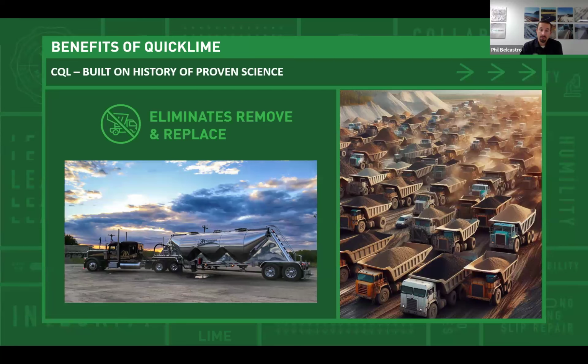But when I go to the sites, I'm one of the few people that are smiling because I know that clay soil is primed for lime. We can modify it. We can get some true stabilization on it. We can use what Mother Nature has put in that soil, the natural pozzolans, silicas, and aluminas, to generate those bonds that we're going to use to generate these needle-like cementitious and pozzolanic reactions for us.